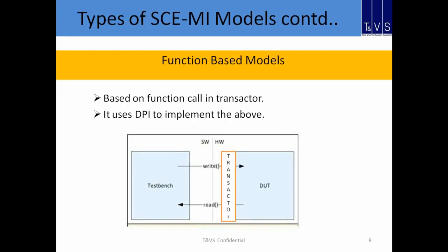Next are the function-based models. These use DPI to implement the SCE-MI infrastructure. Here the transactor sits next to the DUT, and the test bench talks to the transactor, which in turn talks to the DUT.